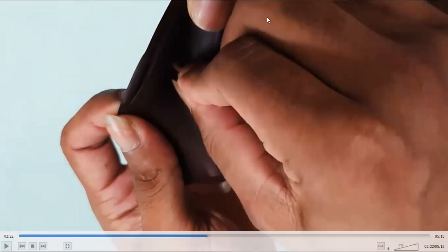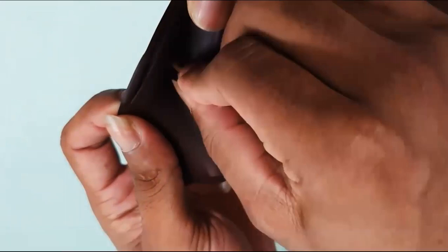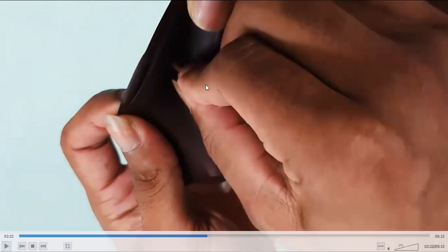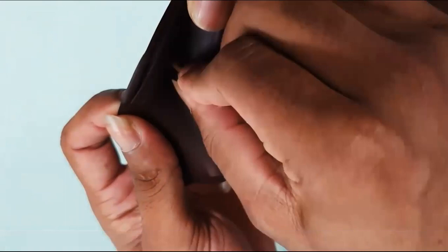So I hope you got the idea. In the membrane, we only have this kind of stiffness. In the plates, since I don't have a perfect example to show you, the perfect example is a slab. There we do not have any membrane forces developed, it cannot take membrane forces, but it can take out of plane loading, because we don't usually see in plane loading in a slab piece.